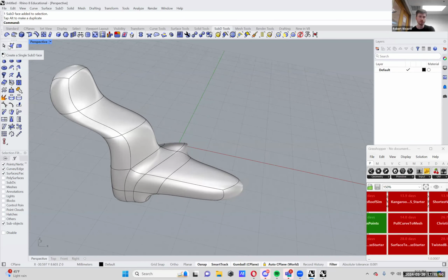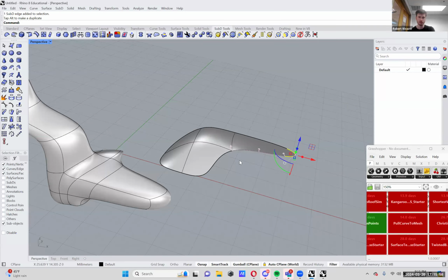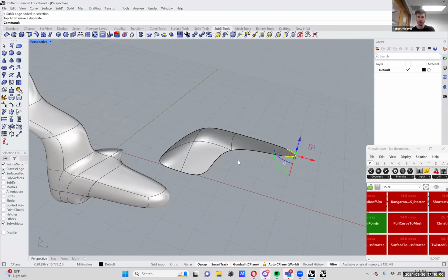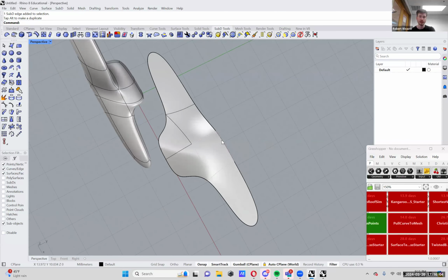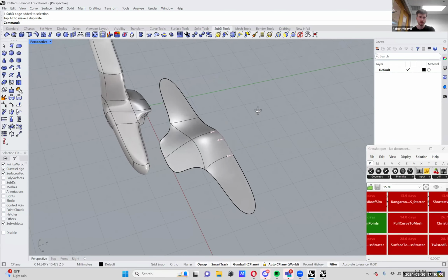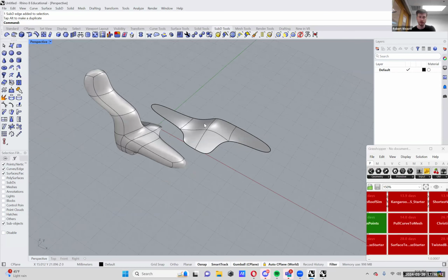You could also create with planes. So this would be like a flat shape, more surface-like. It's not a surface though, just to note, in Grasshopper it's different from a surface. And you could maybe use this to get a cowboy hat form pretty quick. I think there's also extruding options as well. So you can take this flat form and extrude it up to make it solid.